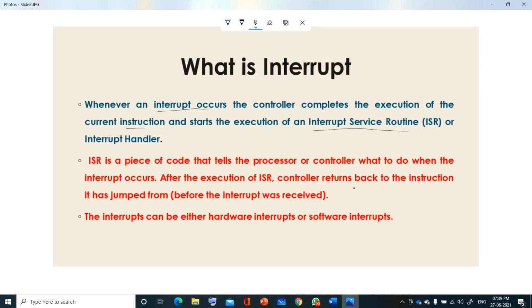See, the interrupt service routine is written in the ROM. Let's say we have a 4K ROM. In the ROM, it specifically says, let's say this is your reset, and we have some interrupts like timer interrupts, the serial communication interrupt, and the hardware interrupts like interrupt 0, INT 0 and INT 1.